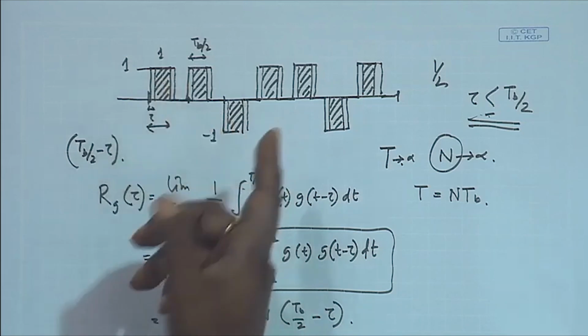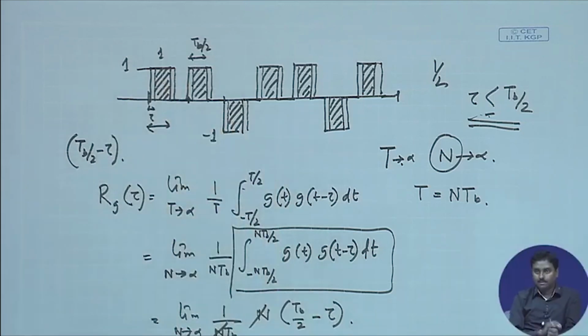So it will now have overlapping with the next pulse, or the next to next pulse, whatever it is. Whatever happens, it is not his own pulse, it will be the next pulse. Now, there is exactly half probability that it will be the same. That means 1 will be overlapping with 1 or 0 will be overlapping with 0, because the 1s and 0s are first of all not correlated and they are equally probable.